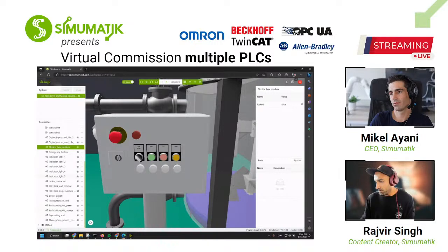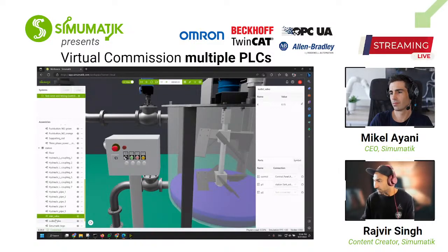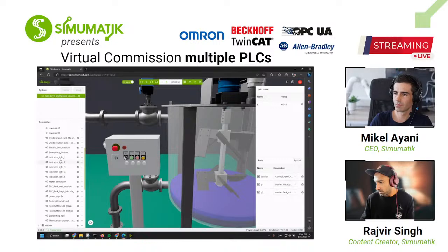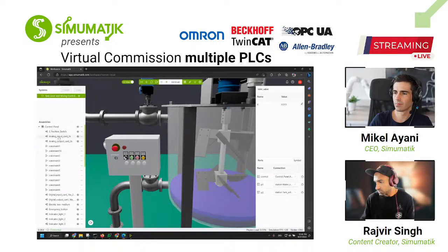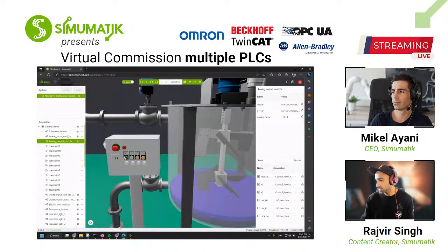Okay, and now for the valves which are here, the inlet valves. These valves are connected to my analog outputs. So if I go to my analog outputs here, which is on the top, we have two variables. One is NS1, analog output 1, data type double, and the second one is analog output 2. And these are the same variables I used in my Node-RED.